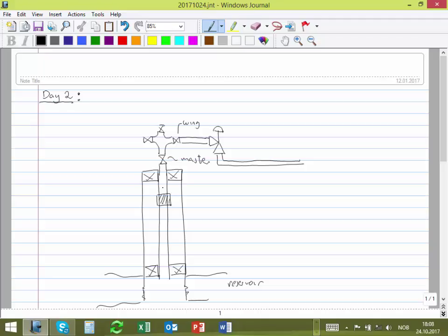And something maybe I didn't mention last time: I told you that, if you remember, to keep this valve open you have to fight and push a very strong spring to keep it open. So you have to have hydraulic power. And how that hydraulic power enters into the well, actually you have to make a hole, okay? And this piece of pipe is avoiding fluid to come, this piece of pipe is isolating the space between the tubing and the casing.